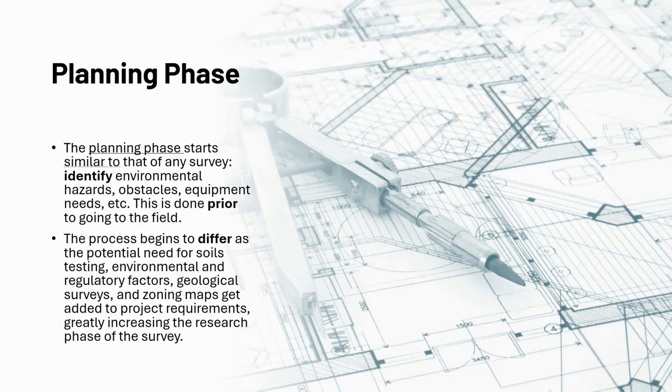That's going to depend on things: are we looking at heavily wooded areas? Are we looking at lots of topography? Can we use drones? Can we use LiDAR scanning? Can we even use GPS, or is it too covered that we're going to have to go traditional? We're going to look at all that information ahead of going out.